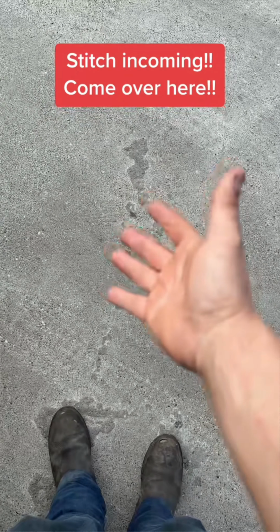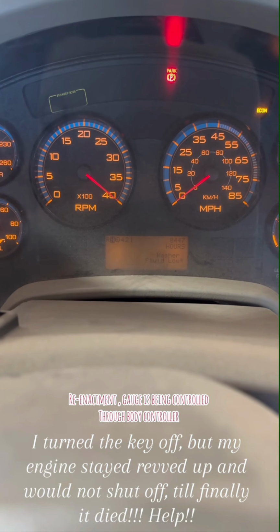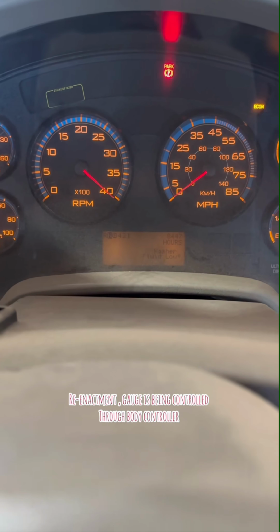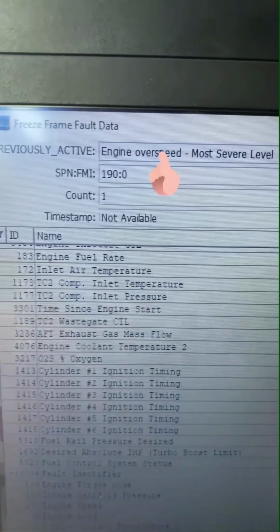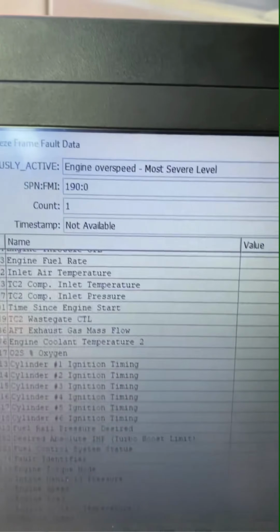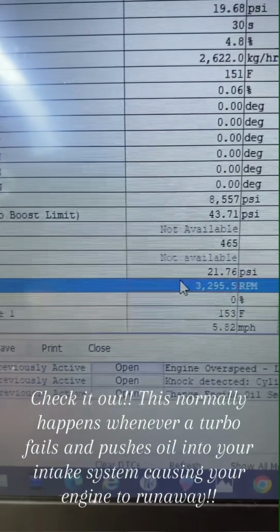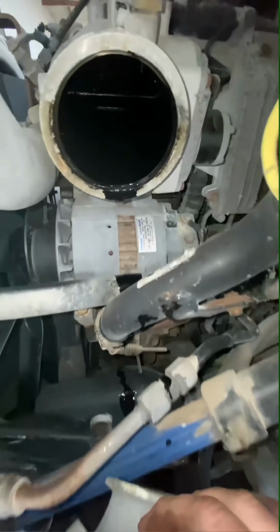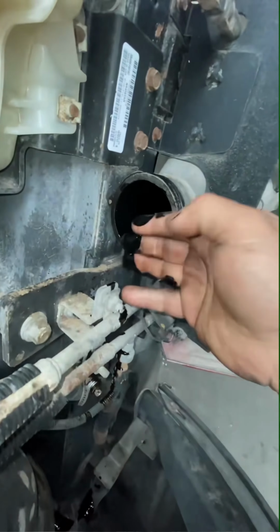Miguel! Come over here. Customer states, when I was at a stoplight, my engine started to rev up on its own. I turned the key off, but my engine stayed revved up and would not shut off, till finally it died. Help! Mechanic says, come over here. Let me hook up to your ECM. Yup, it shows that your engine RPM went way over the limit. Check it out. This normally happens whenever a turbo fails and pushes oil into your intake system, causing your engine to run away. Yes, sir. Looks like that's what happened in this case.